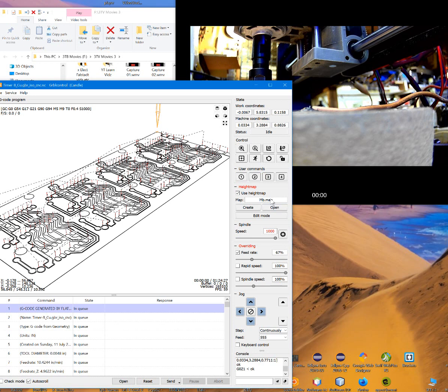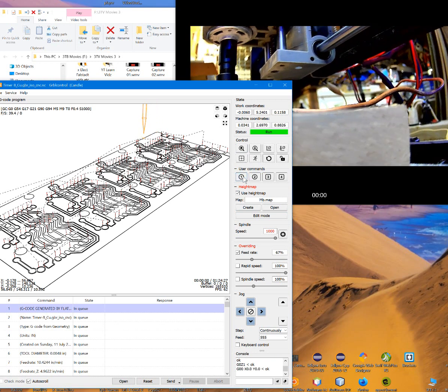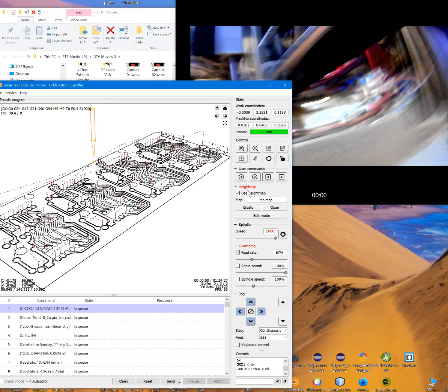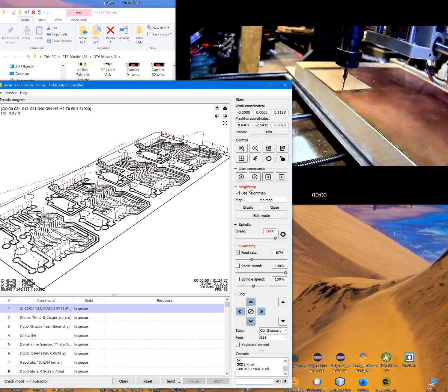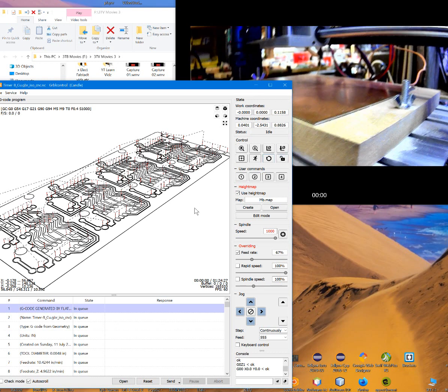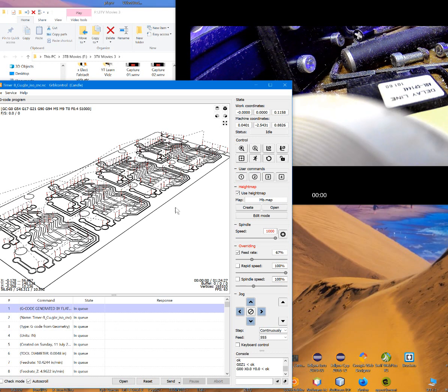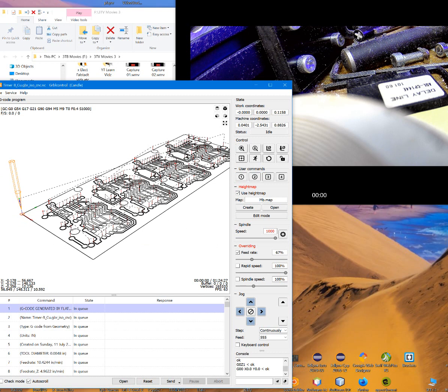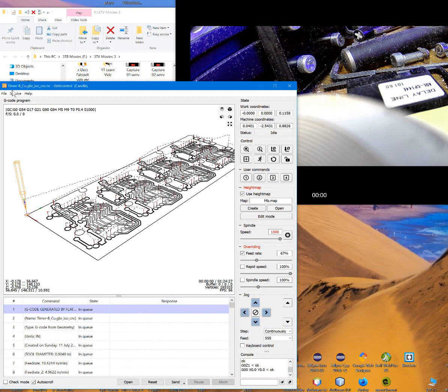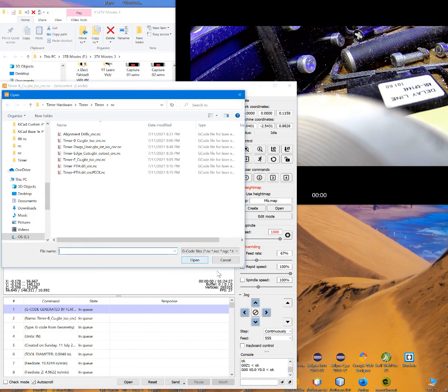and I got my map saved, I'm going to go ahead and zero the tool with my little custom button there. Alright, that's where we're at, and save that. Remember, I've got my drill bit loaded there to do our reference holes, and that's what I'm going to do next. I needed to pull this file up so that I could do the height map, but that's not what we're going to actually machine right now. I'm going to pull up our little reference file.